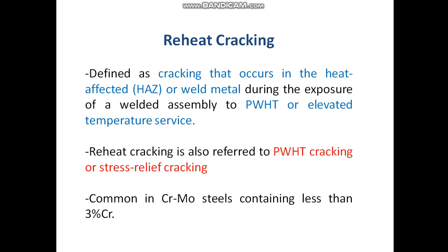Now, reheat cracking is a matter of concern for chrome moly steel. So first, how is it defined? It is defined as cracking that occurs in the heat affected zone or weld metal during the exposure of a welded assembly to post-weld heat treatment or elevated temperature service. It is also known as PWHT cracking or stress relief cracking, and it is common with chrome moly steels containing less than 3% chromium.